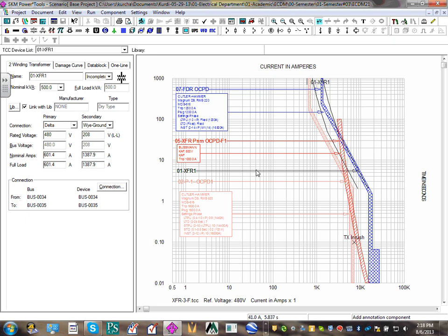Any questions? The reason I'm showing this one is that there's a lot of typical stuff that we do, but when you deal with a transformer, make sure you size correctly. Here's the rule: you want to size the overcurrent protection device as low as you can and match your conductor to it. Does that make sense? That's why I say 125 on the primary and the secondary. Size your overcurrent protection device and match the conductor to it, and 95% of the time you're right. Any comments, any questions? I keep overwhelming you with that one.